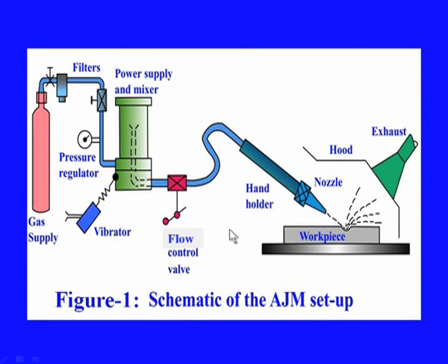And again, the distance from this nozzle tip to this workpiece is also very vital. We will discuss this point later on with a different schematic. Here the other arrangements are shown, like this is the gas intensifier or the gas supply, pressurized gas device. This comes through this nozzle or some gas flow control device, and here is one of the very crucial components in this entire setup, in which the gas and the abrasive get mixed.